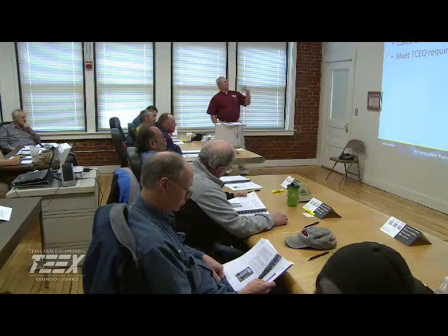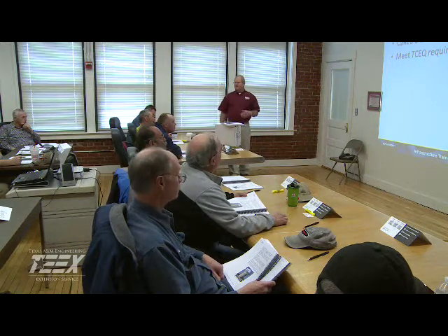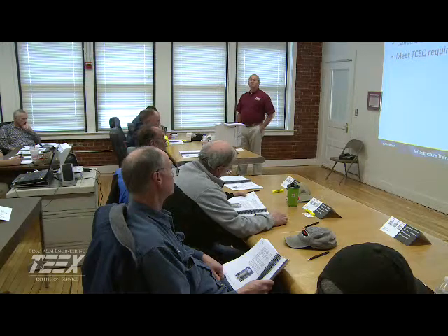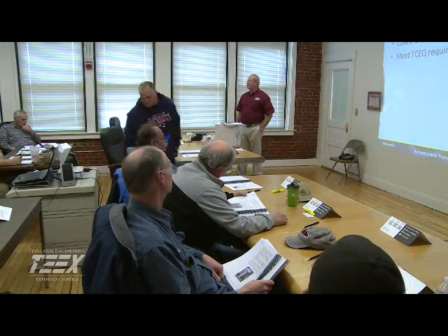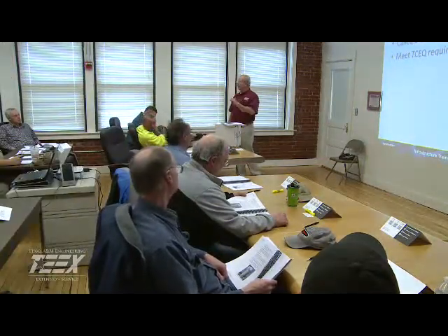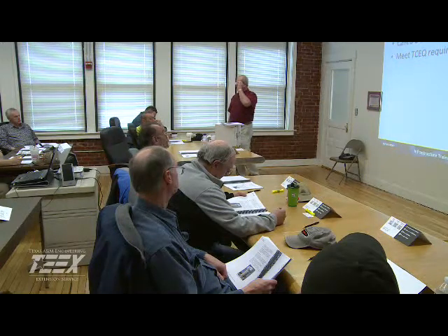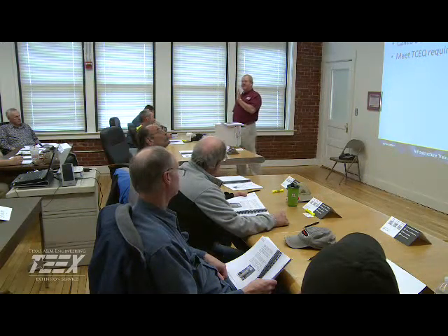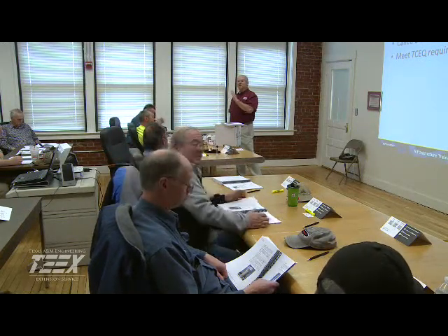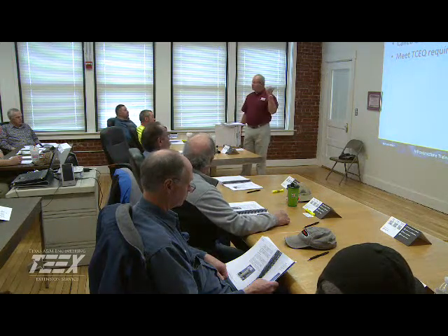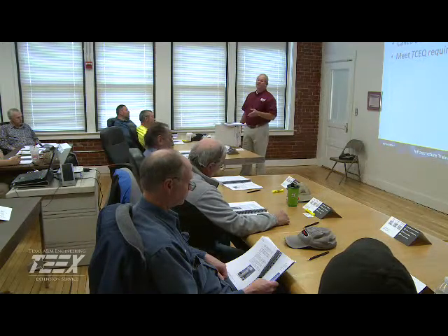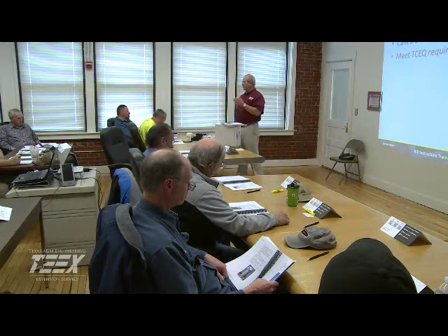And meeting the Texas requirements, the state of Texas requires that every facility in Texas have a minimum of 200 gallons per connection storage. Now, each state can be slightly different, okay? But the EPA mandates that each state determine the amount of water for storage, okay? Now, when it comes to firefighting though, this is only for water supply. But if you're using your system for firefighting to get the best insurance rates,